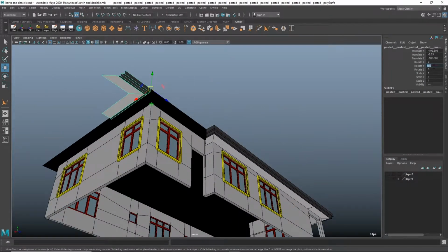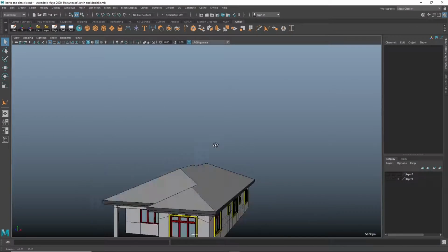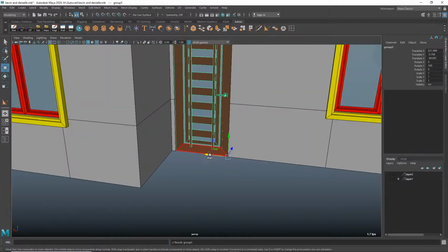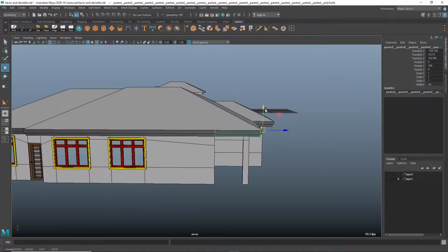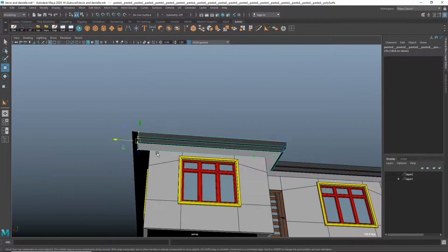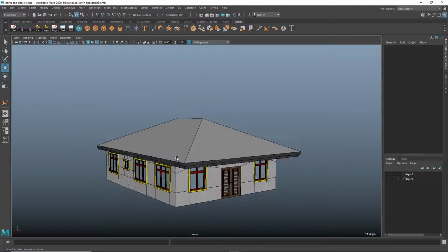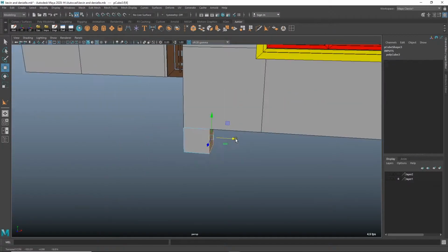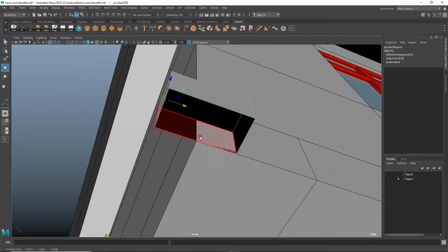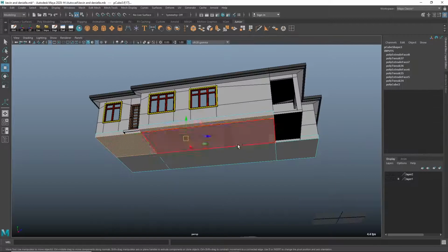You would notice some strange colors. So when you take a mesh from any program into Lumion, Lumion recognizes the difference in objects by the material it has. So if two objects have the same material, when textured in Lumion, it checks it as one. So what I normally do is create new materials for the walls, the windows, the doors, the glass, everything like that, and I just assign it a random color, because the color doesn't matter. When you open it in Lumion, you would see the color, and then from there you could go through and texture it.